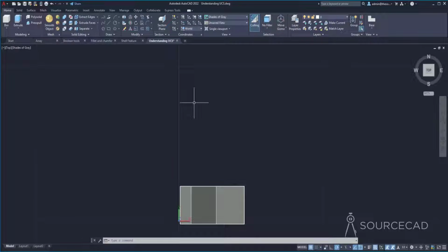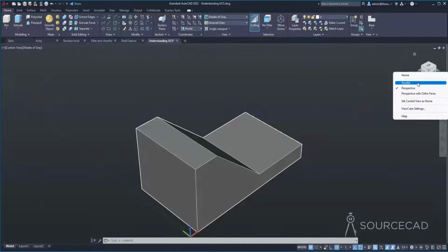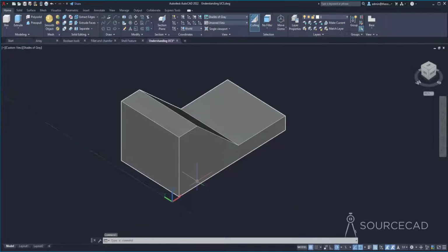So what are the options? Well, the options are also pretty straightforward. If you want to make a drawing on any other plane, simply make that plane the top plane or XY plane. Now let's for a moment assume that I'll first switch to parallel here. Now let's for a moment assume that I want to make my drawing right here on this plane.